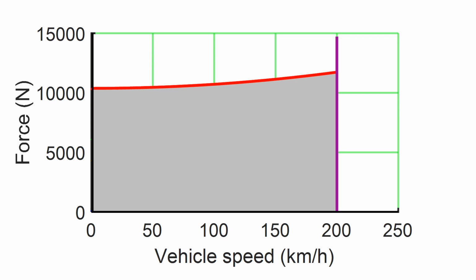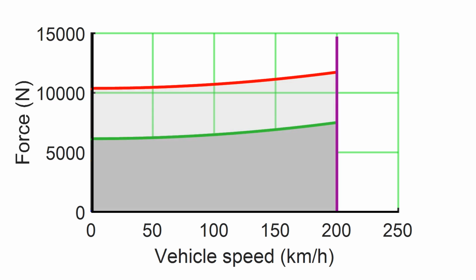Since the powertrain can accelerate 4 meters per second square on a flat road, the same force is capable of accelerating 3 meters per second square on a 10% gradient, 2 meters per second square on 20%, and 1 meter per second square on a 30% gradient. We assume that this acceleration performance on gradients is okay for the car we investigate here.